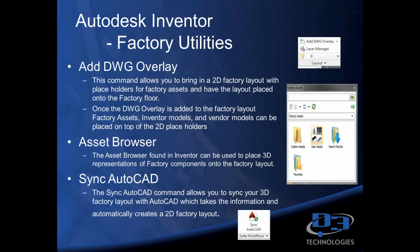All right, so now jumping into the Autodesk Inventor factory utilities inside of Inventor. Again, there's a wide range of tools available, but we're just going to focus on a few of those. The first command that we're going to look at on the factory utilities is the DWG overlay command. This command is going to allow you to bring in a 2D factory layout with placeholders for factory assets, and then have that layout placed onto the defined factory floor inside Inventor. Once that overlay is added to the factory, then we can actually start placing factory assets, Inventor models, and even vendor models on top of those 2D placeholders.